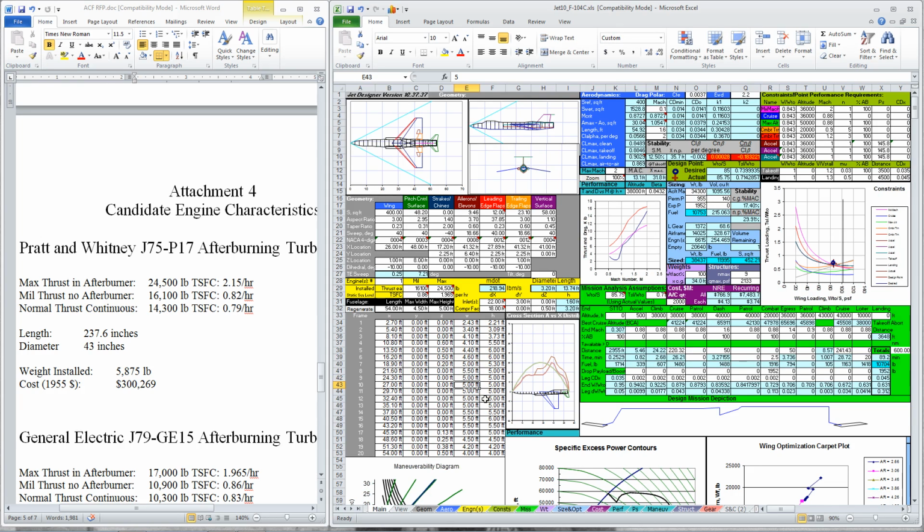Alright. And then the other thing we might do is try to area rule this airplane just a little bit. Here where AMAX occurs at 37 feet or so. Let's try narrowing it down just a little bit. Let's try 5 there. That cut it down. Let's try 5 on the next one. And even 4.5 on that first one. So just a little bit of 4.5 on the next one. A little bit of area ruling cuts down the fuel burn. It does hurt our volume problem, but we can drop our weight.